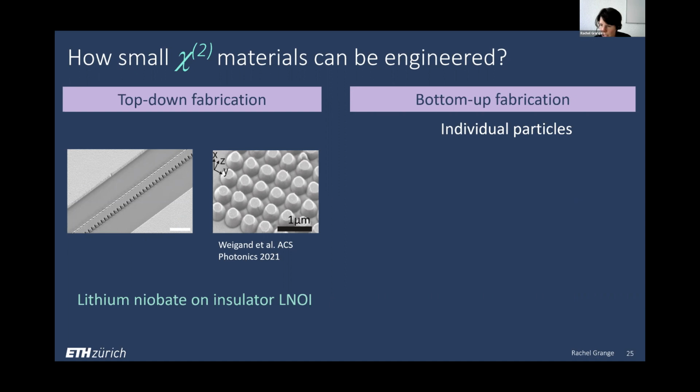So I see a question about the first sample of lithium niobate metasurface, etching with an ion miller rather than RIE or others. So we do argon ion etching, right? We really etch with an ion miller, not with reactive ion etching, right? So not sure I answered the question, but we really do argon ion bombardment of the sample for etching.